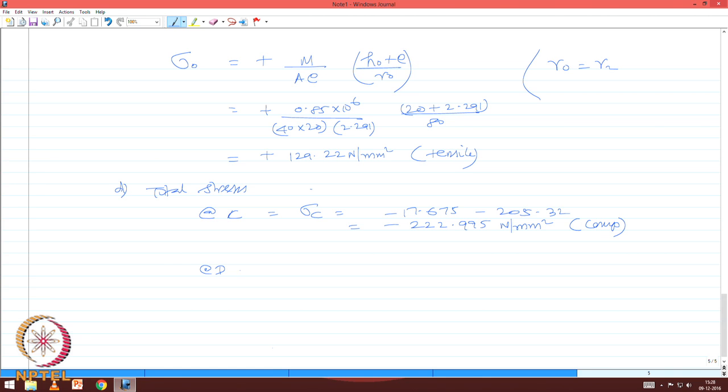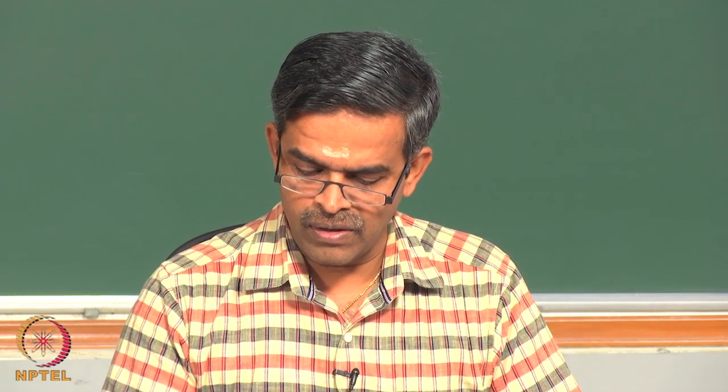At point D, which is sigma D, which is extrados, the direct stress is the same, but the stress due to moment is 129.22, which is plus 111.545, which is tensile.